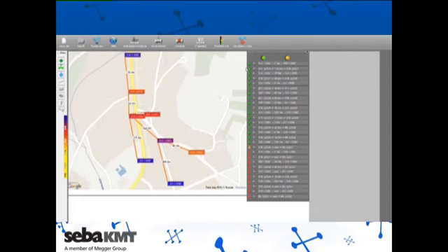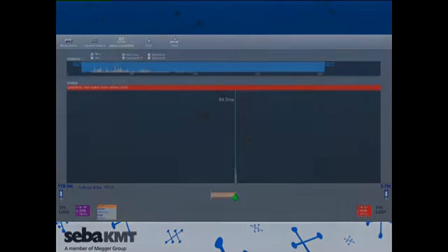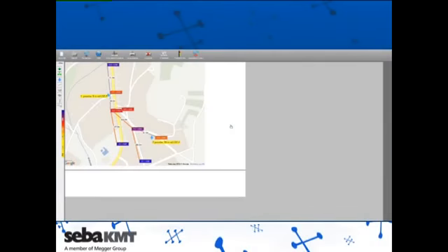This way, we can visualize all significant correlation results in the map view, which enables fast identification of the leak points present. After analyzing the measured data, we were able to identify 2 leak points in this application. One in the proximity of sensor number 5 and the second 20 meters from sensor number 4.